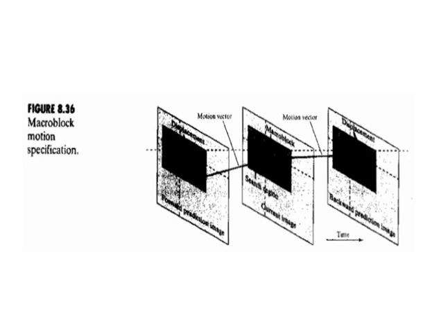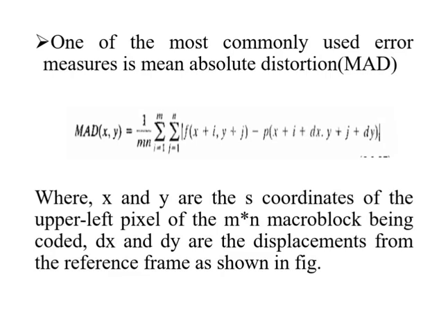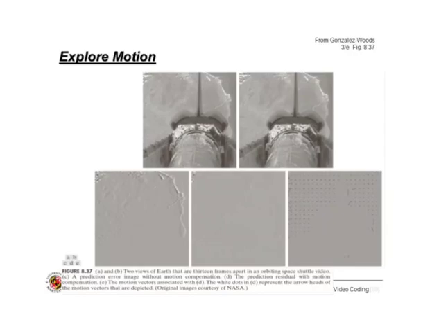As you might expect, motion estimation is the key component of motion compensation. During motion estimation, the motion of an object is measured and encoded into the motion vector. The search for the best motion vector requires that a criterion of optimality be defined. For example, motion vectors may be selected on the basis of maximum correlation or minimum error between macroblock pixels and the predicted pixels from the chosen reference frame. We have already discussed this formula.